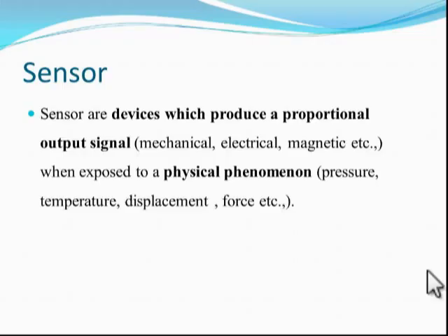So what is a sensor? First of all, we want to know what a sensor is. A sensor is a device which produces a proportional output signal, like mechanical, electrical, magnetic waves, etc., when exposed to physical phenomena such as pressure, temperature, displacement, force, etc.